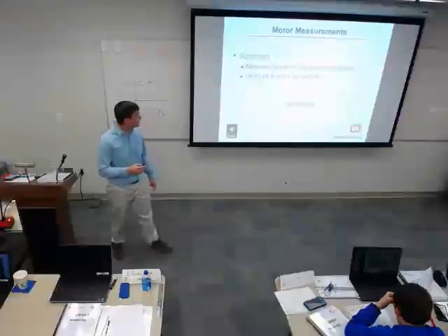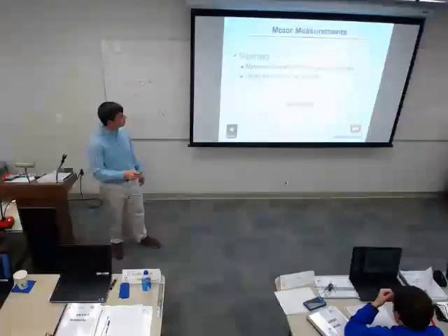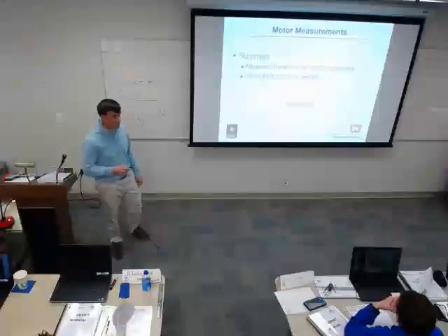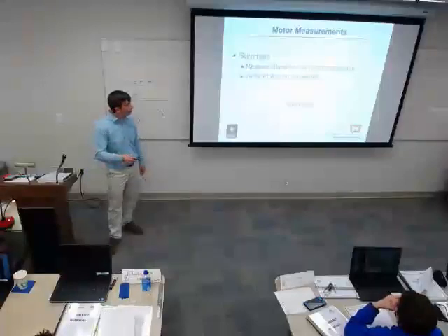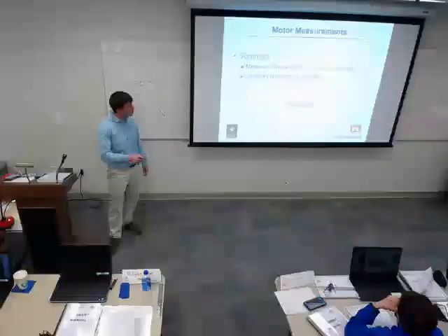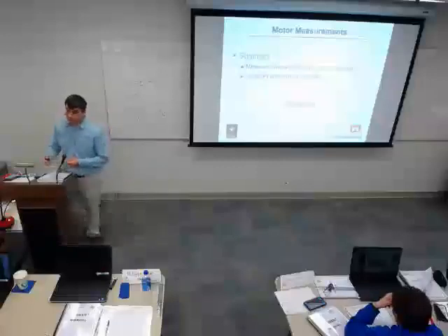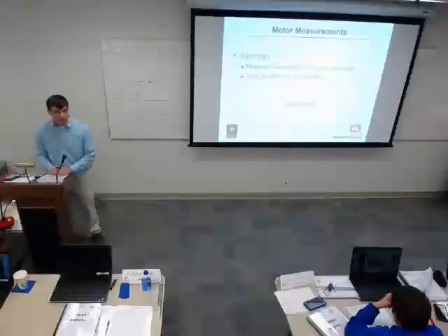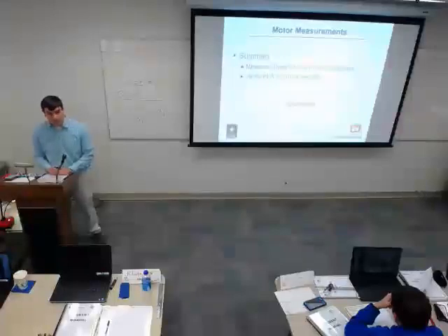Motor measurement summary. Be able to look at that motor nameplate. Hopefully you understand a little bit more about what all those numbers mean. And the big part being, we don't want to exceed the current that's listed on there. And so once again, if a contractor comes to you and says, I just need to get in that service factor a little bit, we don't want that.